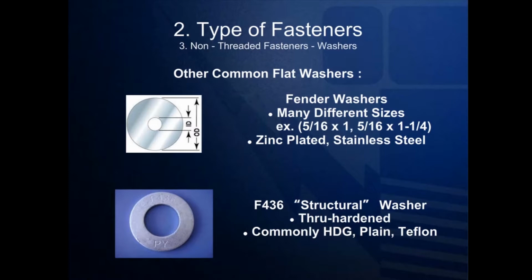In the structural steel market, ASTM F436 structural washers are extremely common. These washers almost mirror the dimensions of the SAE pattern. However, F436 washers are through hardened, thus making them ideal to be used with A325 structural bolts.